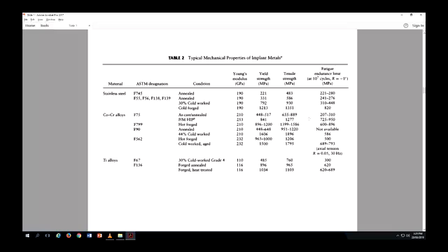And then it's giving you a summary of the properties and the methods by which they have been made. And then this is the ASTM designation. These are the numbers that the standards provide, and each of them determines what composition, exactly what percentage of each element they've got. Based on those, you get certain properties, and it's very important that the manufacturer has actually followed all these details in the standards. Otherwise, you're going to get a faulty, not good quality material.